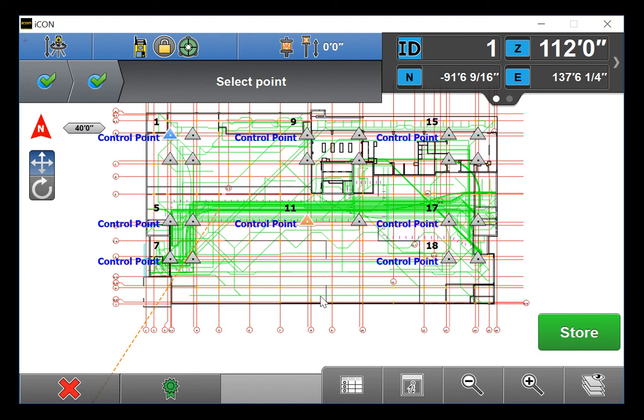If you are still out of tolerance, check the levelness of your total station and remeasure while ensuring that you have the correct points chosen as your targets, your rod is precisely level, and the tip is precisely on the intersection of the control points. If you've done everything correctly and you're still out of tolerance, take a tape measure and check the distance between the control lines to make sure the concrete layout team laid out the control lines properly.